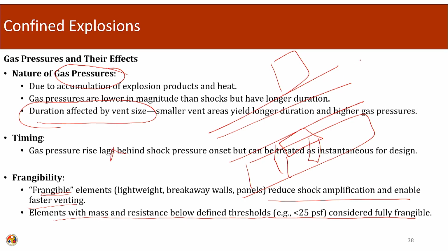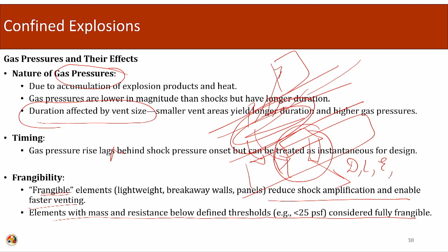So what is said is that if an aircraft comes and lands out here, and if it tries to veer into the two sides, that aircraft might be damaged after hitting this sentry post. Mind here, we are not talking about the damage to the sentry post, we are talking about the damage to the aircraft. So the sentry post is so designed that in the normal dead load, live load, earthquake, and wind cases, it can resist all the loading.